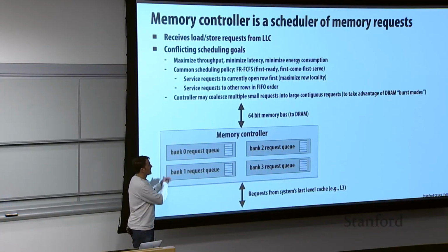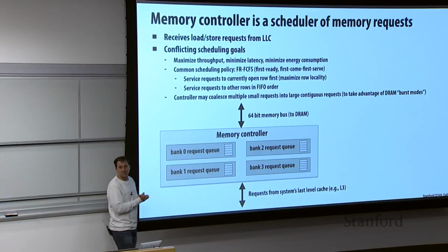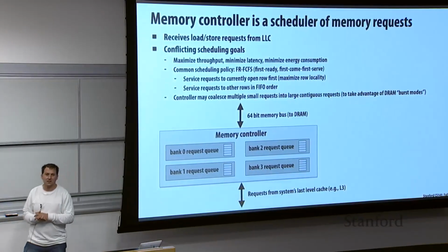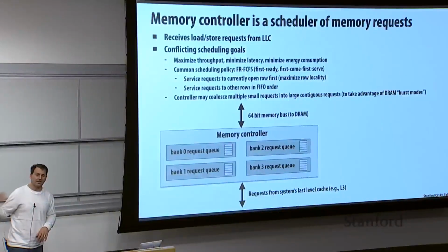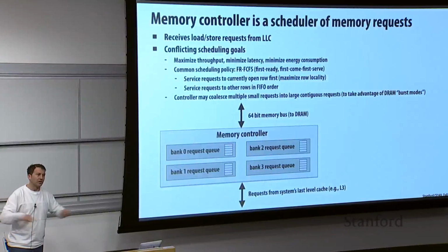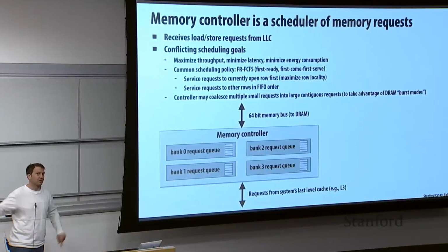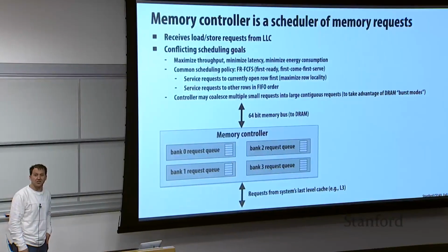memory controller. An NVIDIA memory controller is probably the most complicated part of the chip and could be buffering tens of thousands of memory requests, actually, because everything is bandwidth bound on the GPU. So it's just like, I'm going to wait and see if there's any more requests for this open row for the next 10 nanoseconds. And if anything else comes in, I'm going to let them go to the front of the queue because they're going to be really cheap.